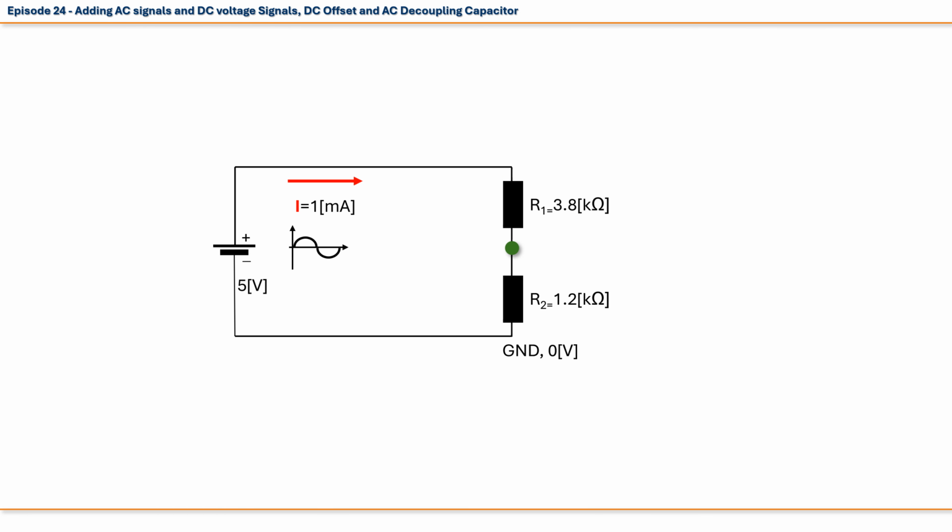In order to marry our AC signal to DC offset, we need a capacitor. Don't worry, at the end of this video, there will be a messy divorce. Now, there is a whole math on how to calculate what capacitor we need. Take it on a leap of faith that we just need a capacitor, as its function is to add AC signal to DC voltage offset. At exit, our AC signal will now have DC voltage offset of exactly 1.2 volts.